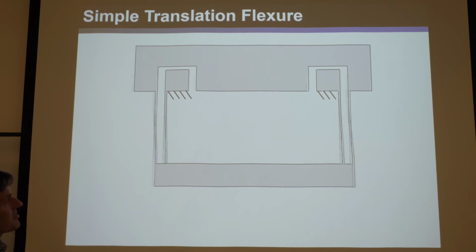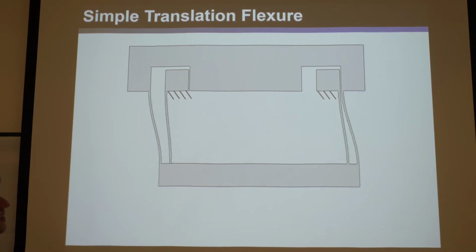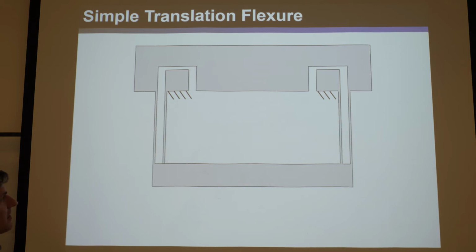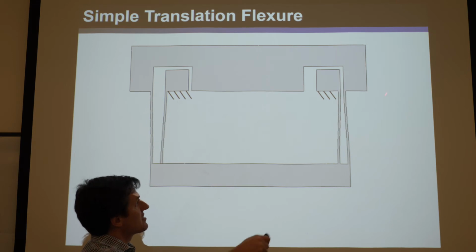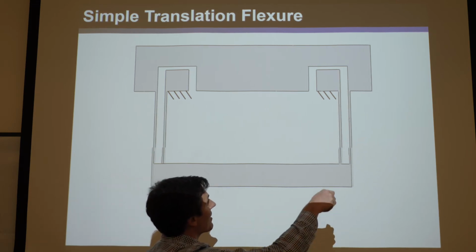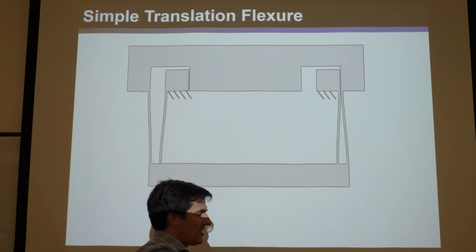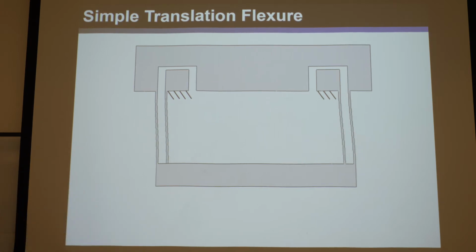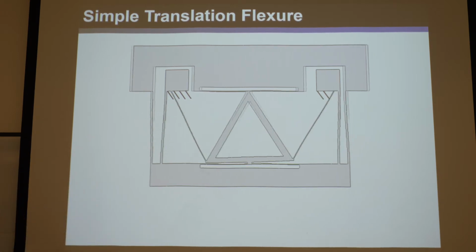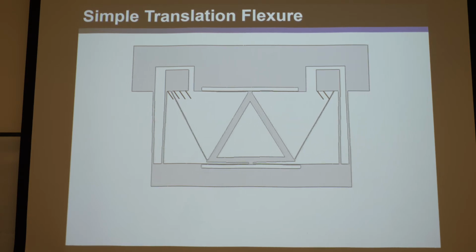There's a redundant degree of freedom. So if you fix, one, they can go in opposite directions, which is bad. And two, if you fix the stage with respect to the ground, this guy can vibrate unconstrained. And there's nothing forcing these guys to move in the 2 to 1 ratio. So if you push, this guy will try and snap back, and it won't be 2 to 1, and there will be parasitics on this. Okay, so how do you fix the under constraint and fix the parasitic error? Well, you can add an under constraint eliminator. Okay, that's what it's called.